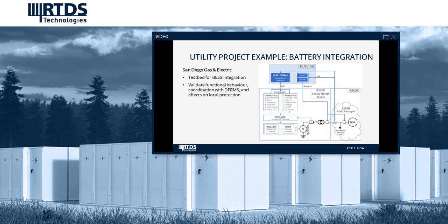And here they're also studying the effects of the new control on local protection by including physical protective relays in the loop. So this really shows the value of a real-time simulator in the context of energy storage. You can connect multiple hardware or software devices in the loop with the simulated network and test interaction and system level coordination with real hardware. So I think this type of study will become more and more common for utilities who are struggling to manage the large-scale integration of storage elements.